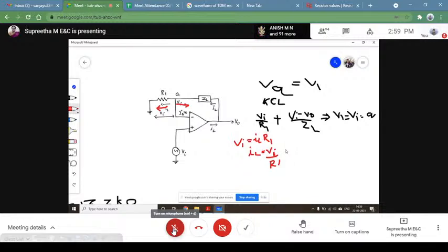You can see here the input voltage I am applying to the non-inverting terminal is converted into the current at the output terminal of your op amp. Is it not? Since your op amp will not draw any current, whatever current is there in the load is the same current which is going through R1.